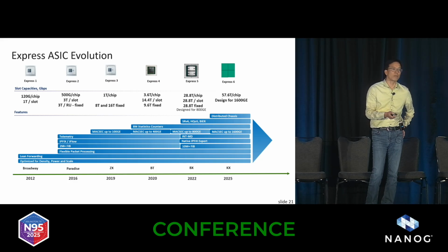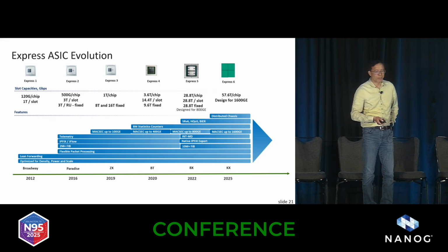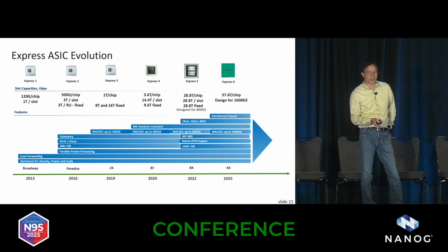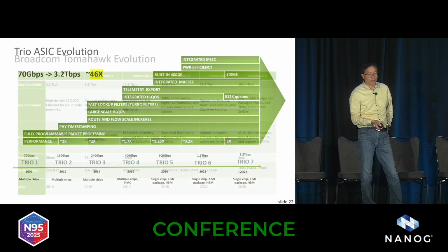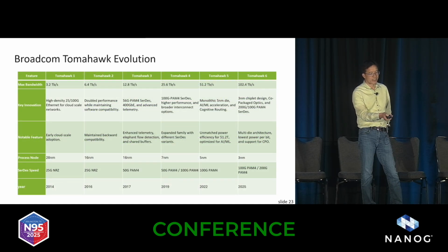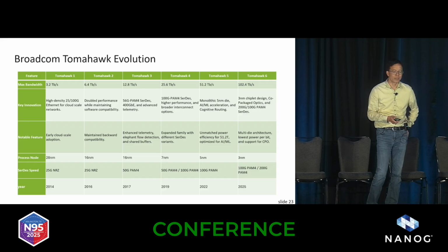If you can get away with shallow buffer, sure, go ahead. Shallow buffer will provide even better cost per bit and power per bit. Tomahawk is in that category, a shallow buffer silicon. They don't provide external memory. If you can manage with on-chip memory, that probably is a very good option.